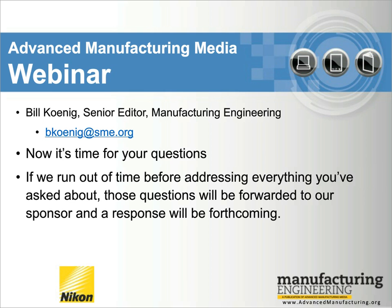And worst case scenario, the smallest machine is actually the least accurate of the bunch. Worst case scenario, you're looking at 3 plus 8L over 1,000. So on a machine that size, that's about 5 microns error through the entire X and Y volume. The Z-axis is a little different. It's actually 3 plus L over 50, so considerably less. The bigger machines are 1 or 2 microns less than that.